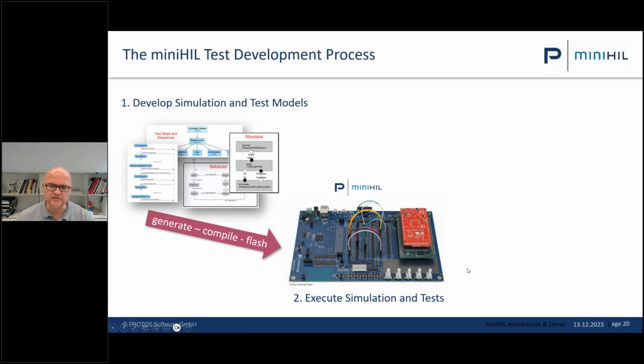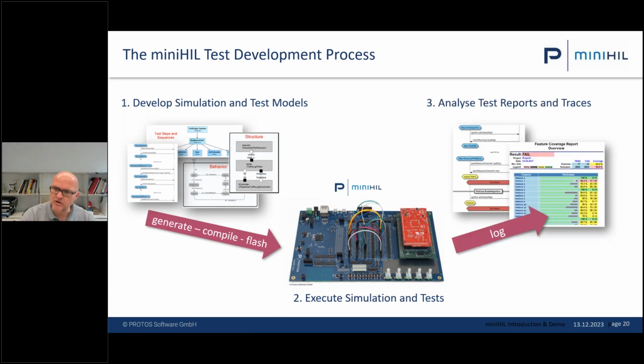And also the test cases we run on this microcontroller, because sometimes you want to know whether something happened after, let's say, 50 microseconds or 100 microseconds. That needs to be hard real time. So the test cases are also hard real time. Then we log the results over USB back to your laptop or to the continuous integration server.